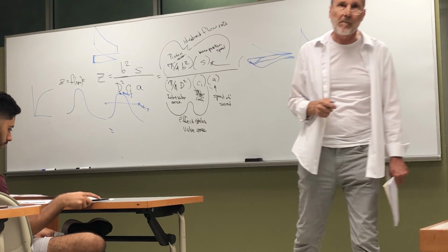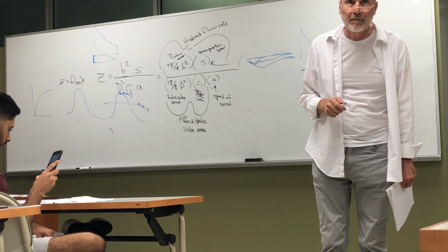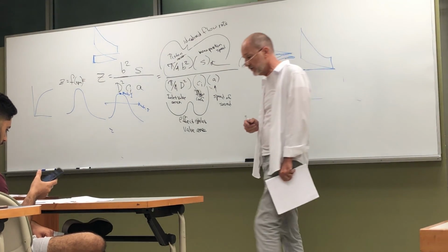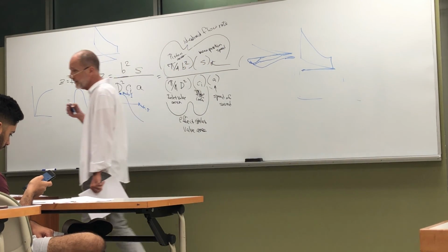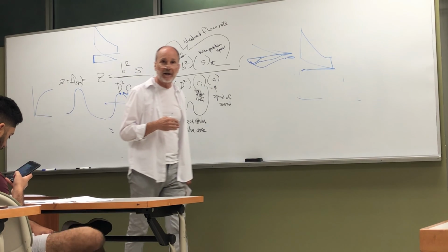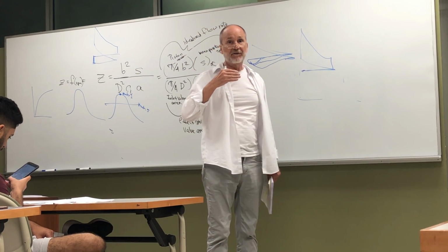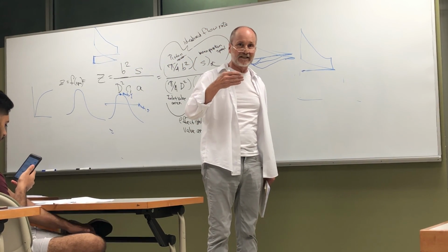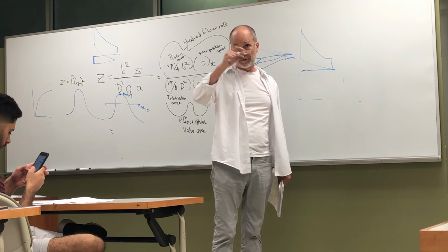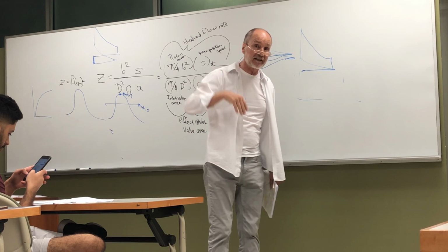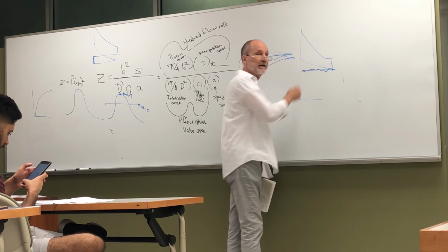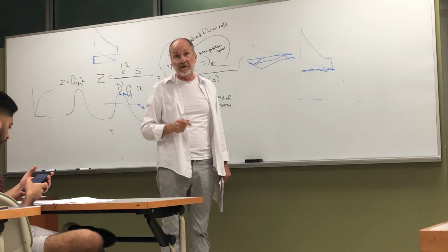When the exhaust valve opens and we're coming back toward the left in the graph, what do the waves represent? Well, during the exhaust there are always fluctuations in pressure. These are in the cylinder. The flow is never completely constant. It's not a stable flow at all. So it changes slightly, and consequently we end up with pressure waves bouncing back and forth in the cylinder, and they show up on the PV diagram.